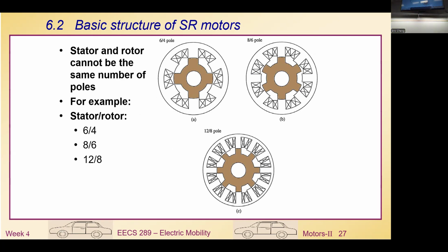If we energize, so this is the winding, this is the winding. When you energize them, then the magnetic flux will go in here. The flux lines still need to fulfill a closed loop. So the magnetic flux passes through this loop and goes back here if you energize this coil and this coil together. They try to minimize the reluctance here. If they are in alignment, then the flux will go through them more easily. But if they are displaced a little bit in angle, then the alignment force will force the motor to rotate until it becomes aligned.